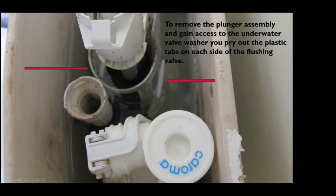Whereas if you put in a brand new one, they're getting a brand new one. It should be fine and last for X amount of years without any hassle. So it might cost them $80 or $100 plus your labor, but you and the customer are getting a guaranteed result. Yeah. With the underwater washer, you just take out the flushing mechanism. Unless it's broken, you don't need to replace it. Pull the old washer off and stretch and slide the new one on.